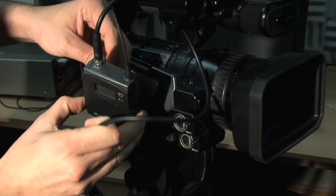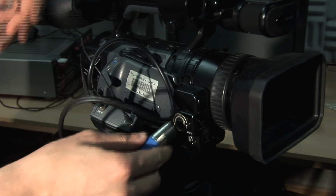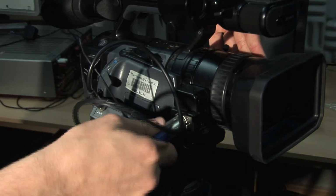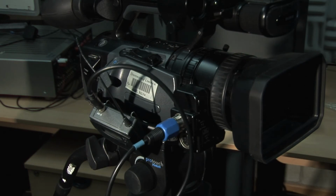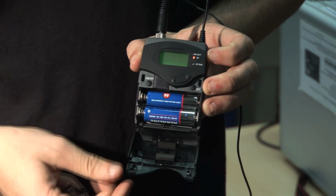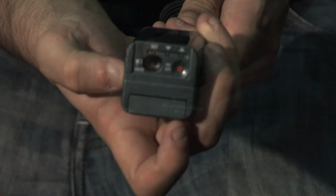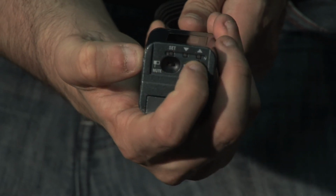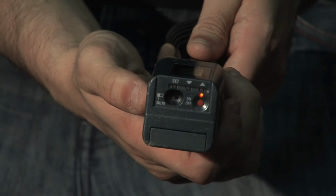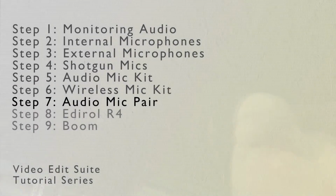First, you must plug in your receiver to the XLR input and turn it on by pressing the button behind the battery panel. Next, you must turn on the mic you wish to use by pressing the on button. For the lapel mic, it is in the same place as the button on the receiver. The power button for the handheld mic is on the bottom of the base. The range of these microphones varies from 10 meters to 150 meters, so test the mics in the environment before you film.